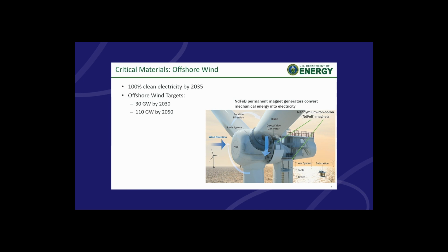You can look at other configurations. You could put a single stage gearbox in there and shrink the generator a little bit. But gearboxes tend to break down. If you pass a wind farm, you might see one's not spinning. It could be because of curtailment, but it might be waiting for a gearbox repair. And so when you have offshore wind, you don't want to have to repair a gearbox, right? So that's why we prefer this technology.